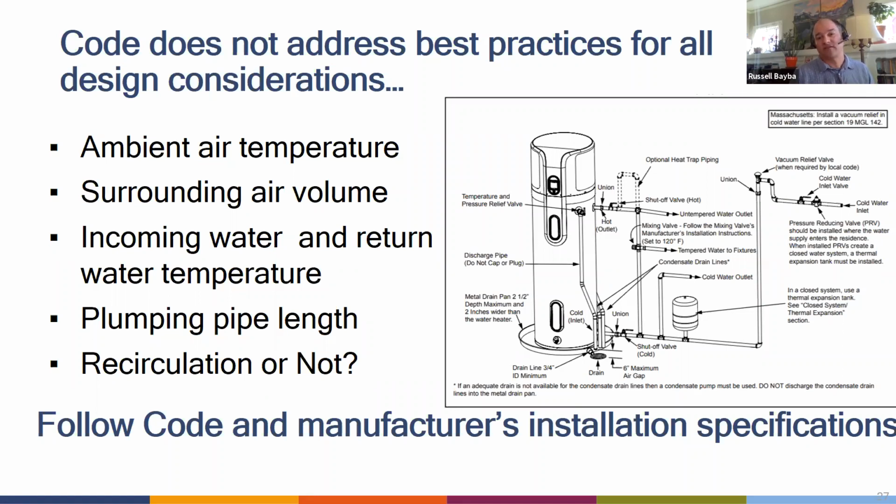So it's extracting the heat. And so it has a COP, which actually ranges from 2 to 3. And I think, Amy, it might be higher now, but it's the efficiency compared to an electric water heater is 2 to 3 times, and for a gas, it's even more than that.